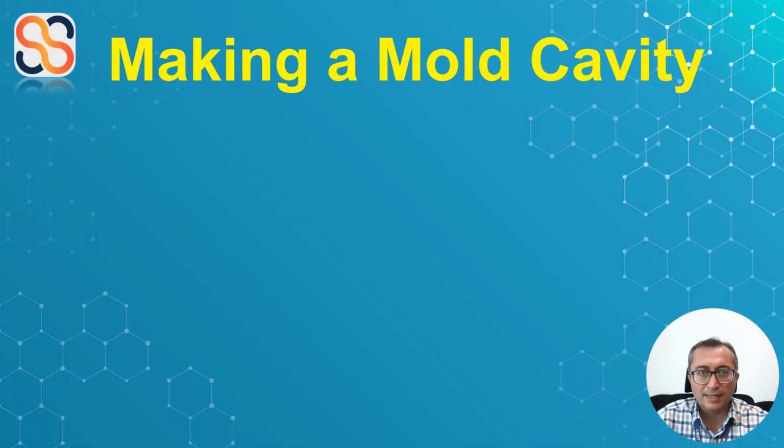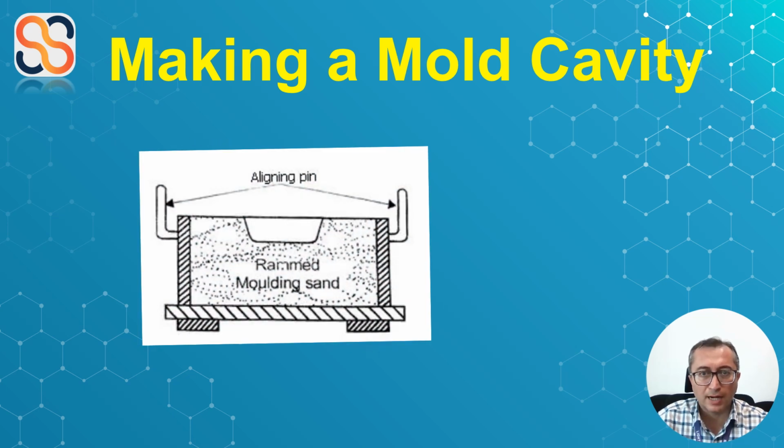Alright, let's continue with the process of creating a mold cavity. First, we roll the drag over and sprinkle parting sand on top of it, as you see here. This helps separate the cope from the drag later. Next, we place the cope pattern on the drag pattern and make sure everything is aligned using the pins.